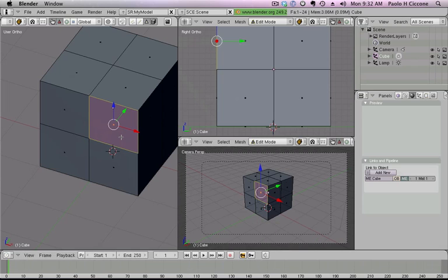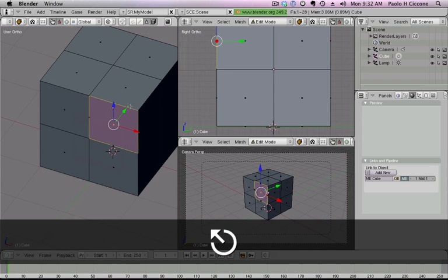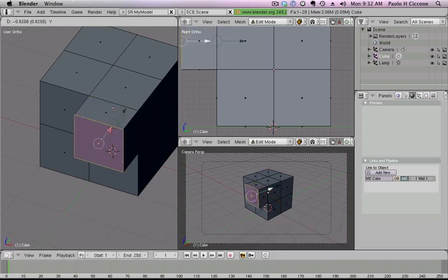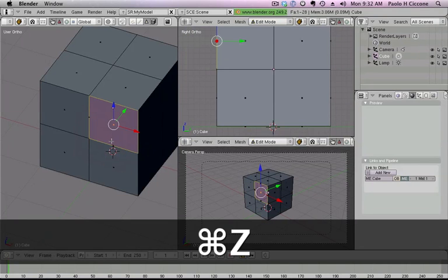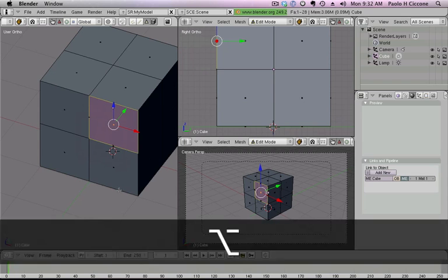In Blender, very conveniently, the extrusion mechanism is started by pressing E for extrusion. So if I have this face selected and I press E, now I can create an extrusion of that face. Let me press ESC. So now I didn't move the face. Now the extrusion happened. I created this additional piece of geometry, but everything is flat together.